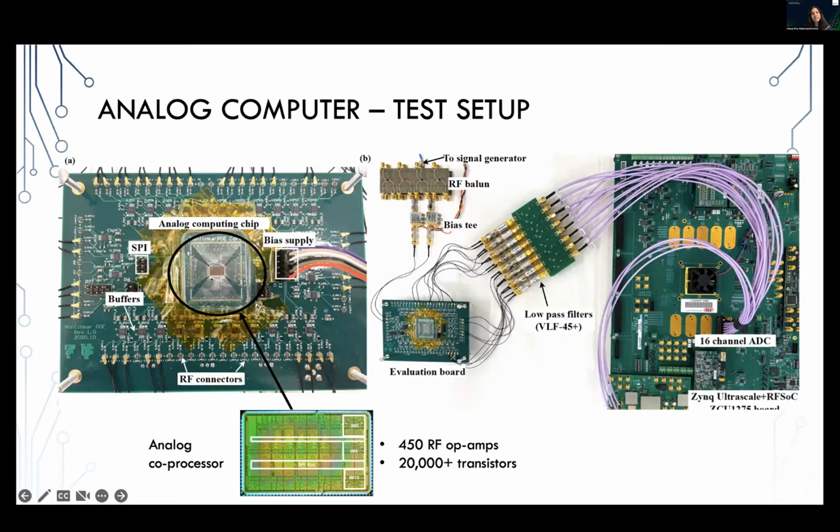This chip is actually a slave device, and the master device in this system is a computer. So the host computer programs this chip using a serial peripheral interface. We have a SPI connector on this board, and this SPI is controlled using a microcontroller. And then the board has other peripheral components such as off-chip amplifiers, and also a power supply and power regulator network on the PCB.